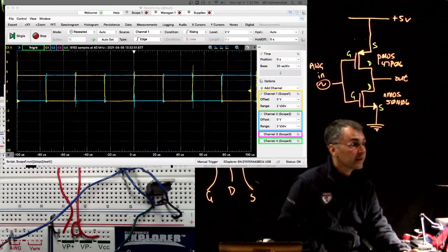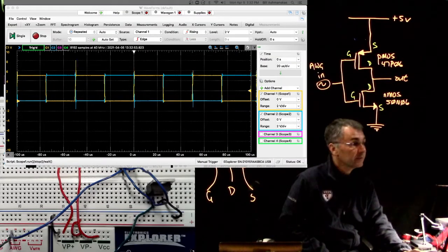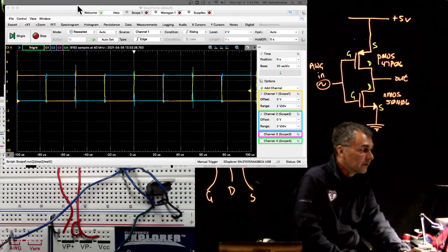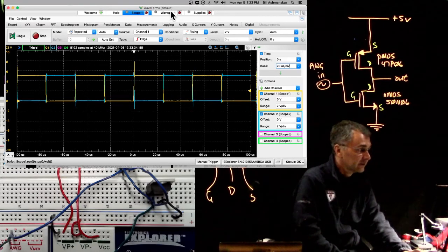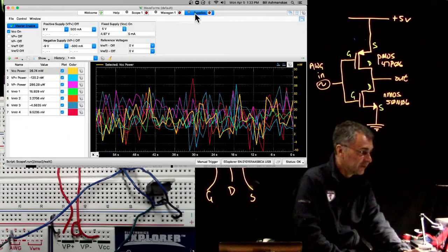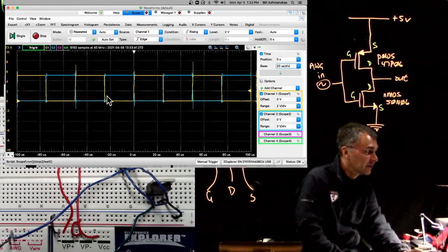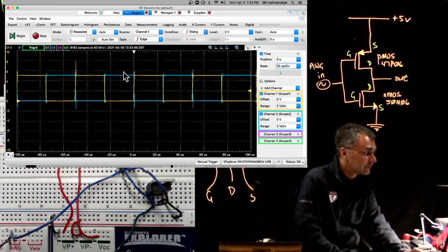And we were looking at the waveforms. Let me just see what the script wants us to look at. We were supposed to try a very low frequency to see how well it works, but it already works quite well at 20 kilohertz, so maybe I won't go down to 1 kilohertz because it'll continue to work well there. Let's instead go up to higher frequency. I think this is a frequency where the NMOS with the original 10K resistor was starting to fail.